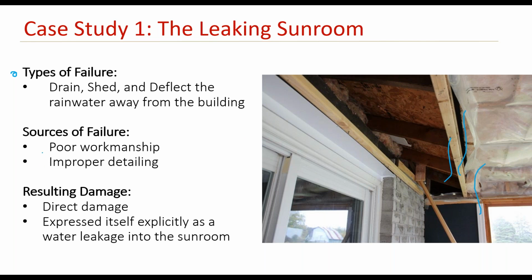We also had another source of failure, which was the improper detailing, and that was by using shingles on an almost flat roof, or a shallow roof that is not supposed to have shingles, and this is a non-code compliant practice, so that's another source of failure.